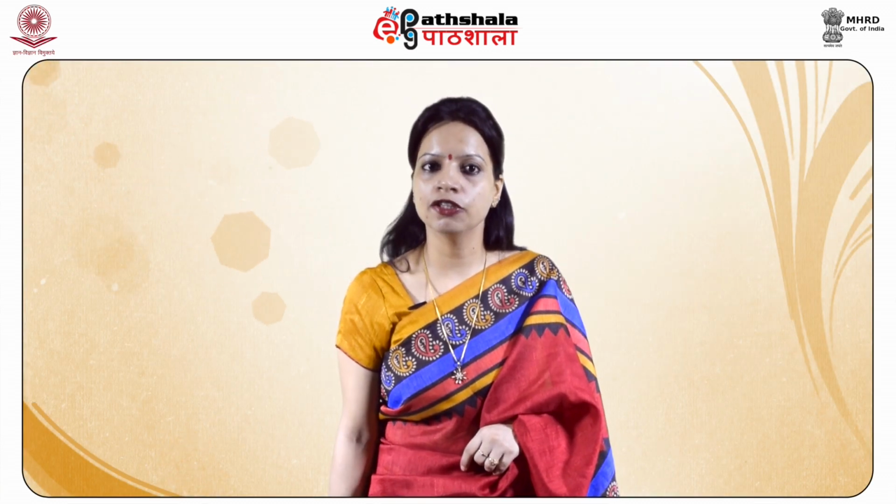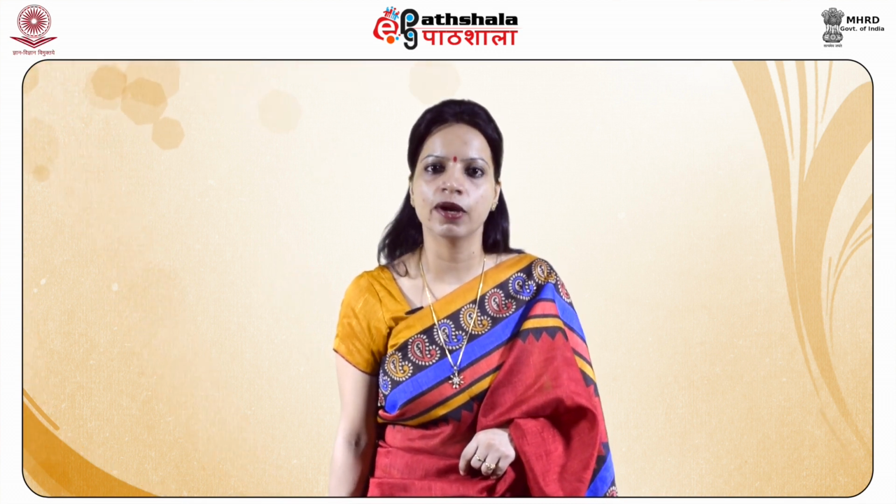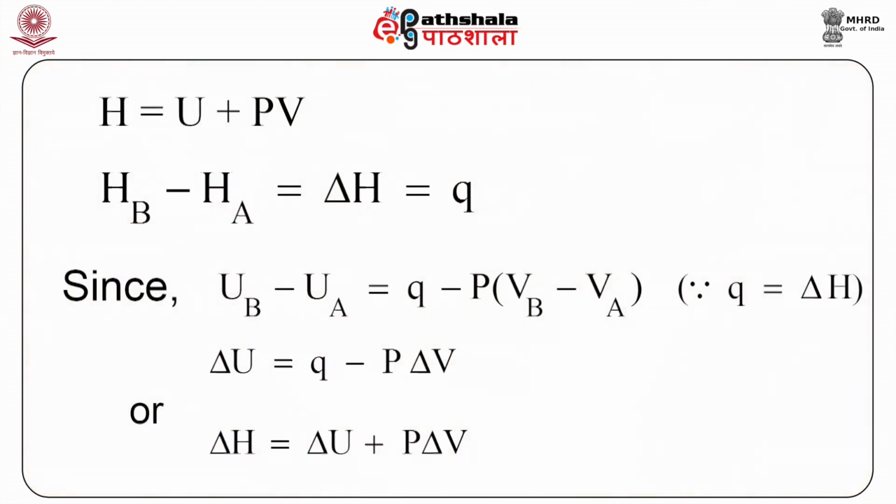The quantity U plus PV is called enthalpy and is designated by H. So we have H equal to U plus PV, that is, it represents the total energy stored in the system. Since U, P and V are definite properties, therefore H is also a definite property. HB minus HA equal to delta H is equal to Q, which we can get from the equation.